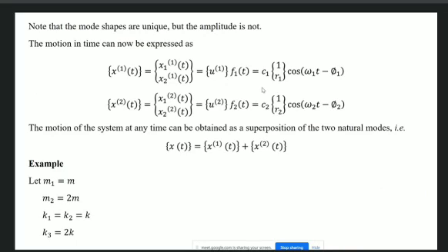Okay, so then our next attempt will be to find out the characteristic equation. That means the characteristic equation in terms of omega. Since it is a 2 by 2 matrix, we will have it in terms of omega square, or omega square we can denote by lambda. So we will have a quadratic equation in terms of lambda. So you know how a quadratic equation will be. Can you write that equation in terms of lambda for this particular problem?